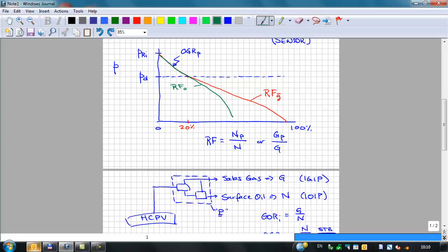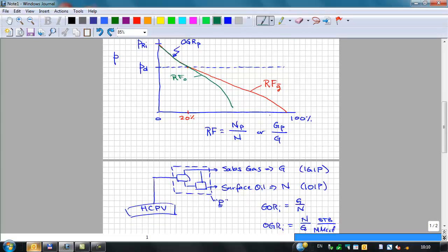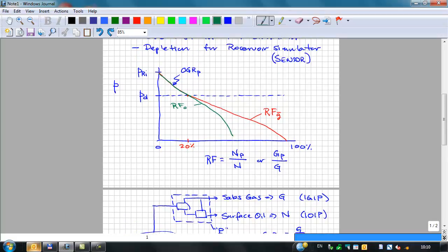That's why you don't revaporize. To revaporize at a low pressure, you have to inject a bunch of dry gas. There's a nice paper by Standing, one of the last papers he wrote, Standing and some people in the 1950s, I think, 60s maybe, on gas cycling at low pressures. Now this is what it'll look like, the type curve of performance for depletion gas condensate.